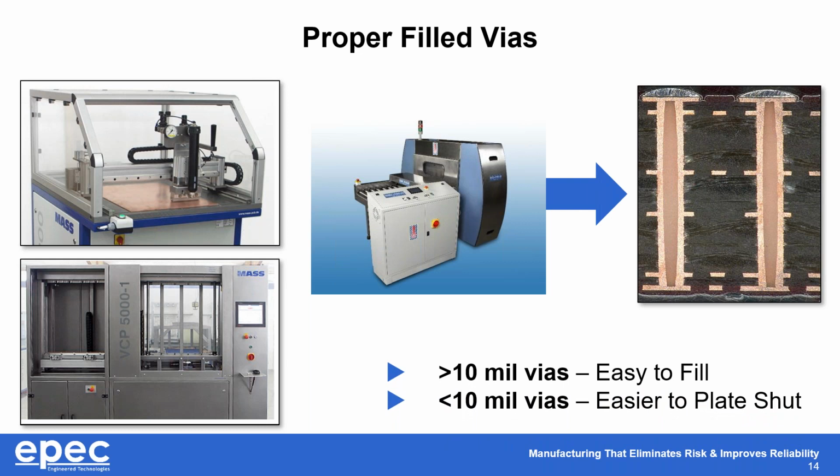And just so that everybody understands, from greater than 10 mils to 18 mils, it's really easy to fill, right? The hole is big enough. You can absolutely do it above certain sizes, it just doesn't make sense. But 10 mils and above, it's pretty easy. Less than 10 mils, it may be easier to plate shut. Depending upon, 8 to 10, it gets a little hairy.